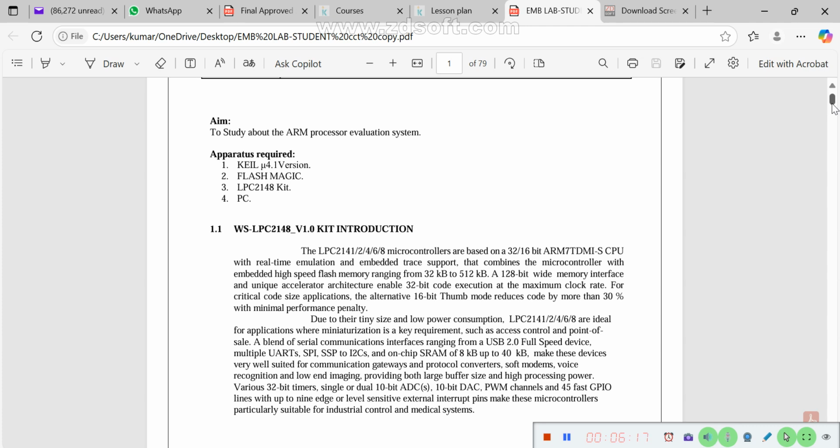In I2C, for example, we have a total of 8 bits. The last bit is used to send the read/write information, and the remaining 7 bits carry the address data that is transferred. After receiving that information, the receiver provides an acknowledgement to the transmitter.